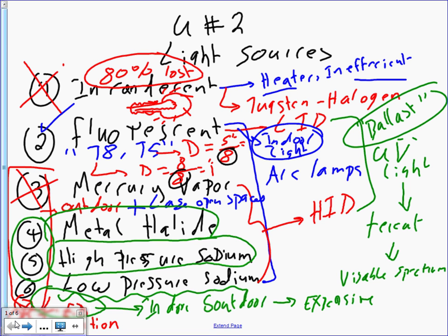So, minutes of warm-up. This curve shows you the minutes of warm-up, guys, for the light output, lamp voltage, and lamp amps. I don't know if you guys can see, as the voltage starts going up, lamp voltage, look at the voltage going up, up, up. As it reaches 100%, like 277 volts, the light output is also going up, and the current is going down. Can you guys see? You have an inrush on it. When you start, you have 160% of the full load current, inrush. And then it goes down all the way after 5 minutes or so.